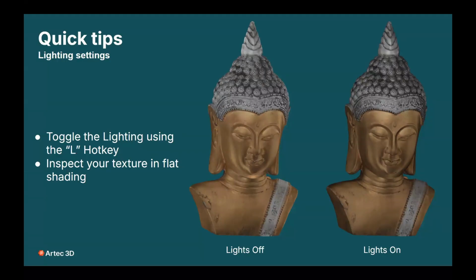Lighting inside of the scene can hide, it can mask some of the imperfections on your texture, because you will see the shadows inside of the scene, which do not relate to the texture of your specific object, such as here. So you won't be able to understand if this shadow is a problem with your scan, or if it is something coming from the lighting in the scene.